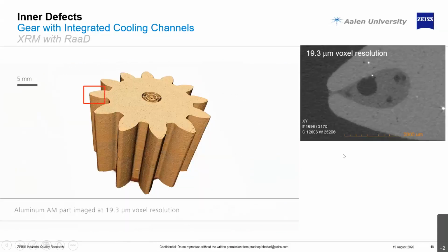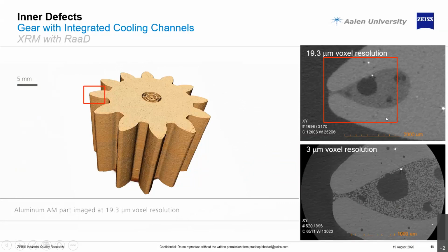And as we start looking at the details, in the first image where we saw the whole gear, we could see this part. It looks like a blob. I know that should not exist. We start seeing some of the higher density material here. And using high resolution imaging, you can start looking at whether the powder was completely cleaned up or not. And here we find basically this is the agglomerated powder, which is sitting in the corner. Heat affected, slightly agglomerated powder. So again, cleaning or depowdering, if it is an issue, then these are the type of images that might be of use.